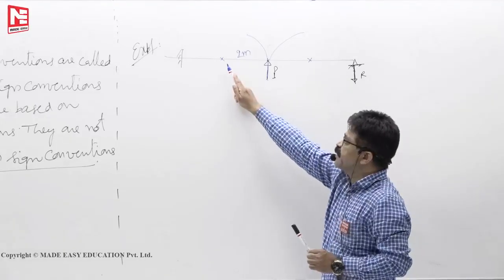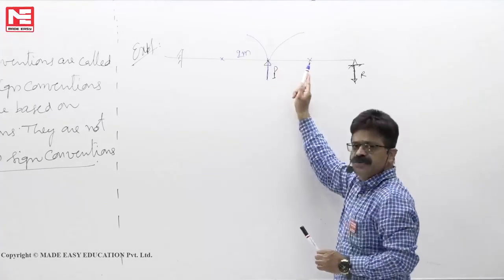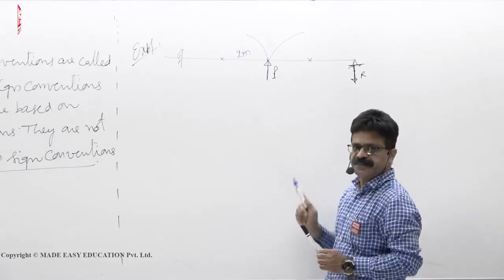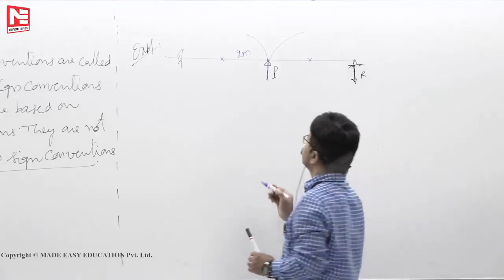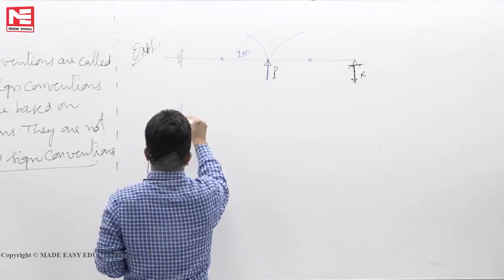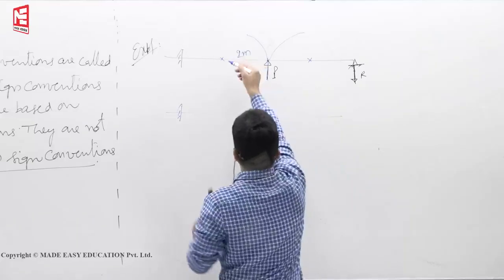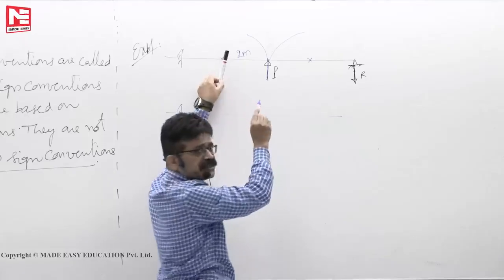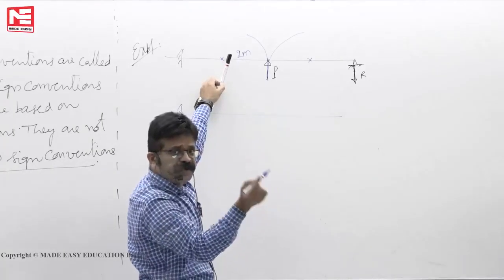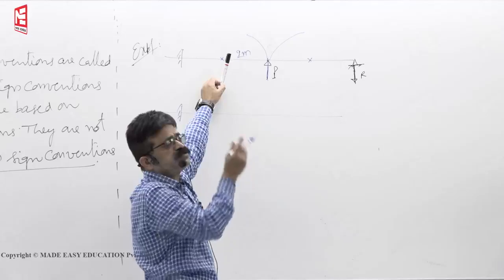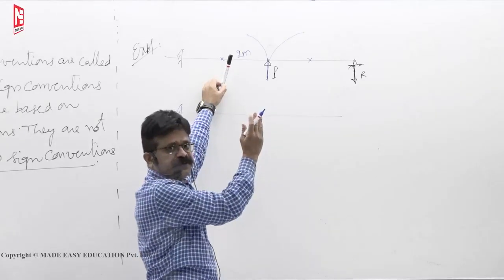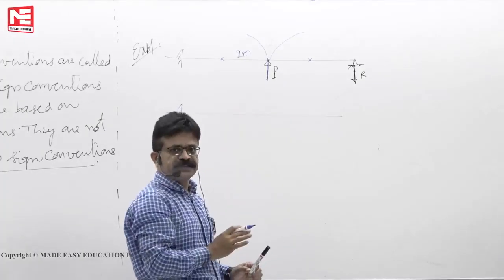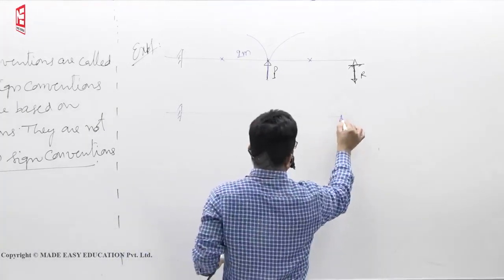That means whether you stand here or here, wherever you stand, this upward force always gives positive bending moment. Same thing we have written. Suppose, as a second example, the net moment may be different. This produces positive bending moment, this downward reaction may produce negative bending moment. If the negative bending moment magnitude is more than the positive bending moment, there can exist a net negative bending moment. Maybe it is hogging, but due to this alone, there must be positive bending moment. So is the case here.